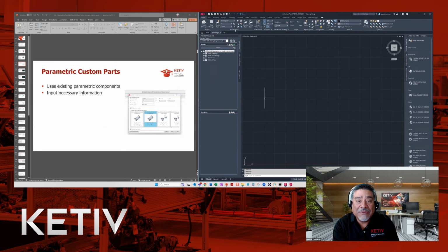But out of the box, Plant 3D does come with pre-existing specs and catalogs. So some of this is already built in. What you're seeing right here is what's going to be provided initially when you first open Plant 3D. You have these specs available here. But unfortunately, all the time, this is not going to facilitate the needs that you might have for any customized parts or anything that's kind of out of the scope of what you normally would use, out in the industry. So that being said, that's where it comes into play that you're going to need to create custom parts.